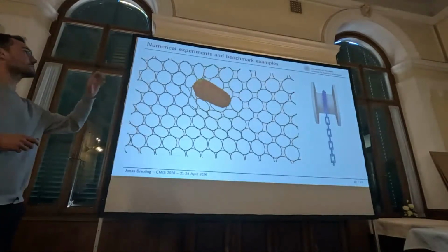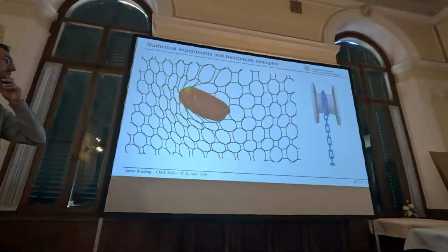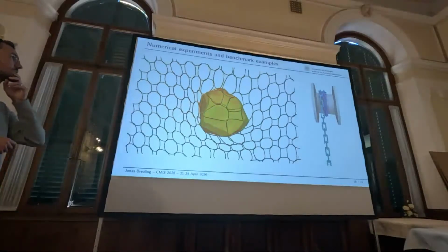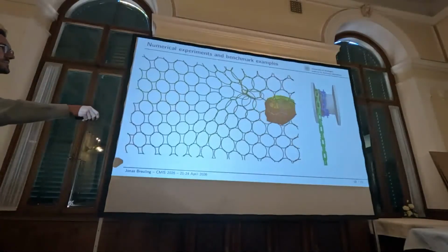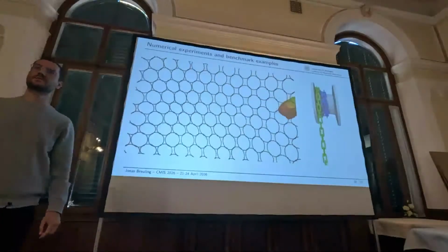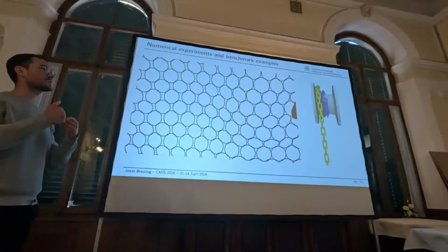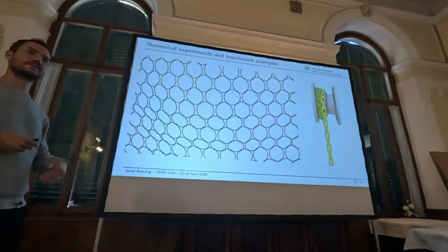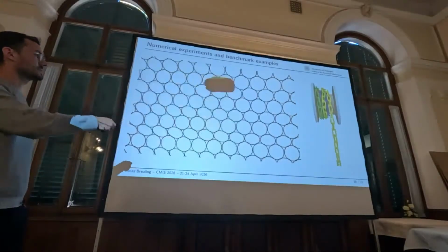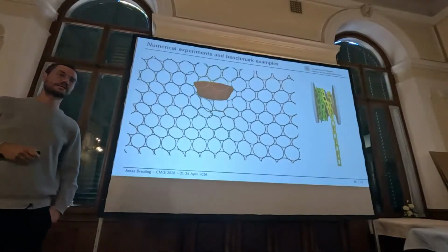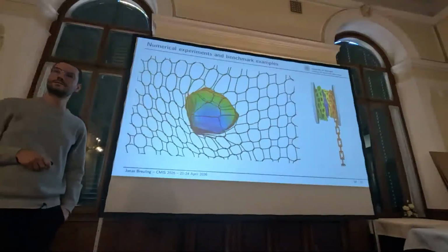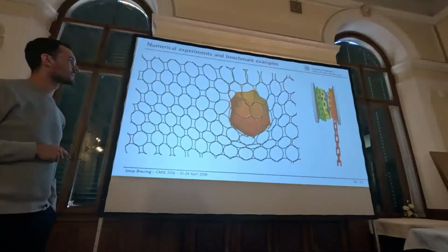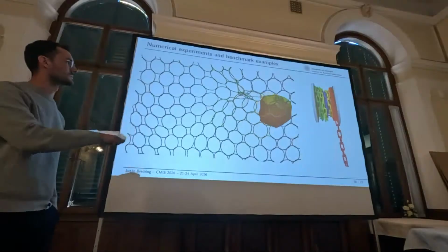The goal was to have a rockfall barrier net. I think this was a quite good test here. It's a very large boulder, and you see in the end something has gone wrong here with the collision detection. I think it's due to the non-convex shape, so there's some strange thing happening. In the end, it pulls out the rope, but that was the only boulder I found on the internet for gravity. So ignore this here.